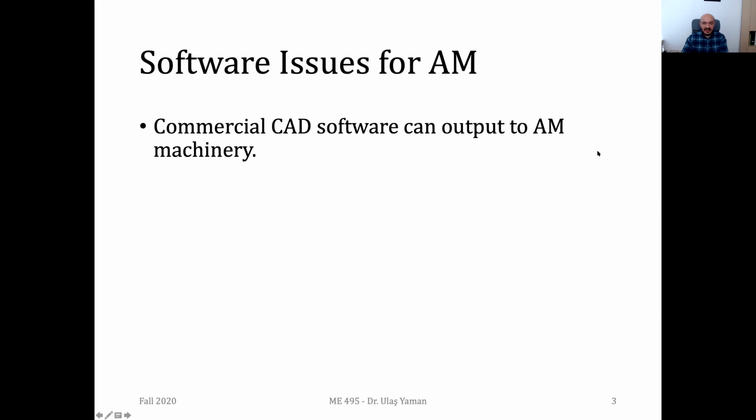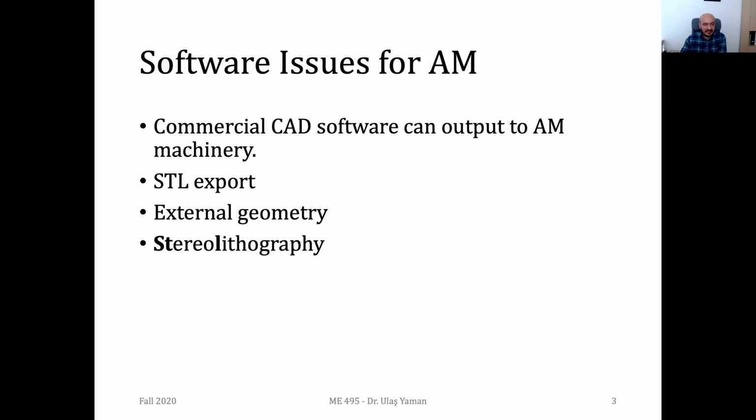As you know, we discussed that in the second chapter, in the generalized pipeline of additive manufacturing. At the beginning of this pipeline, we make use of CAD software to design some parts which are to be fabricated on the additive manufacturing machinery. And then we convert these models into an STL file, which is composed of meshes, and it just has information about the external geometry. As you know, we don't have anything related to the interior.